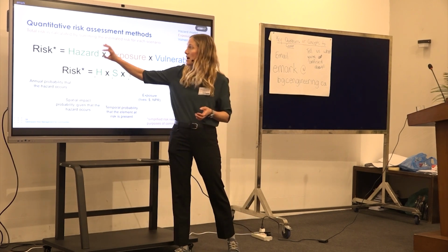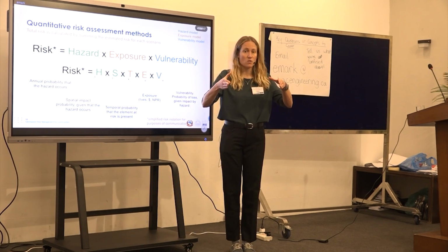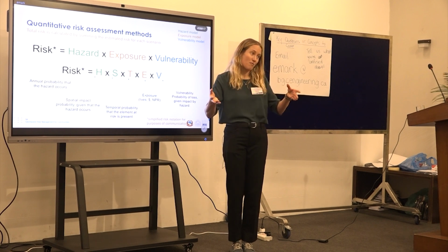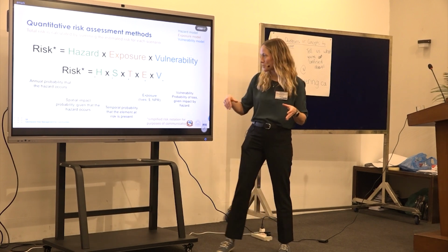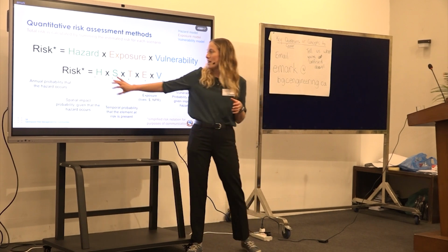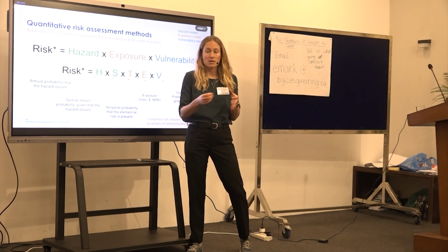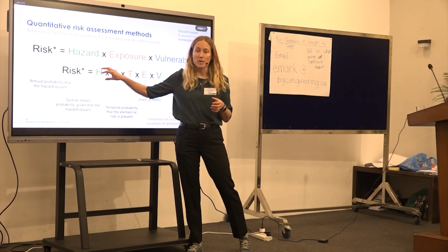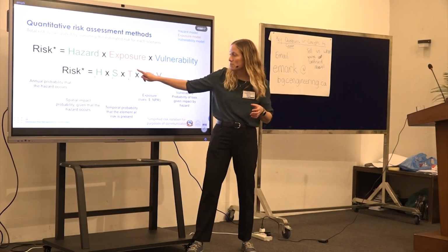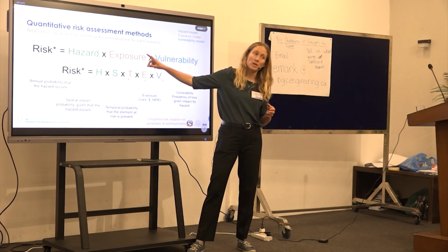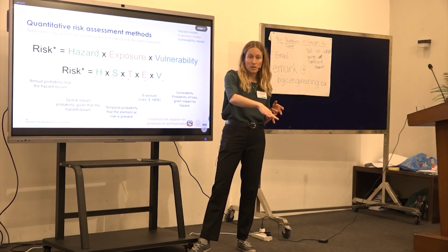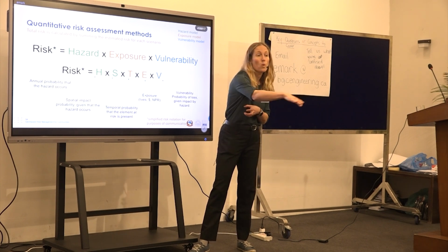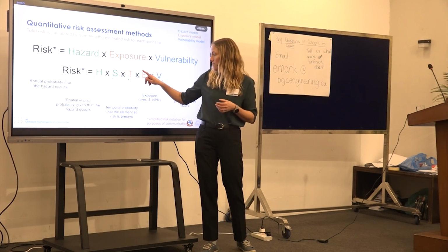So first, the hazard scenario is defined. We're calculating risk for, let's say, a 100-year, let's make it a rockfall, because otherwise I keep going to debris flows all the time. 100-year rockfall. So we know that 100-year rockfall has a certain size. We're going to calculate the annual probability, that's the 100 years. We can figure out the spatial impact probability using different runout modeling tools. Where is that event? Given that this event has a certain size, where is it going to go?